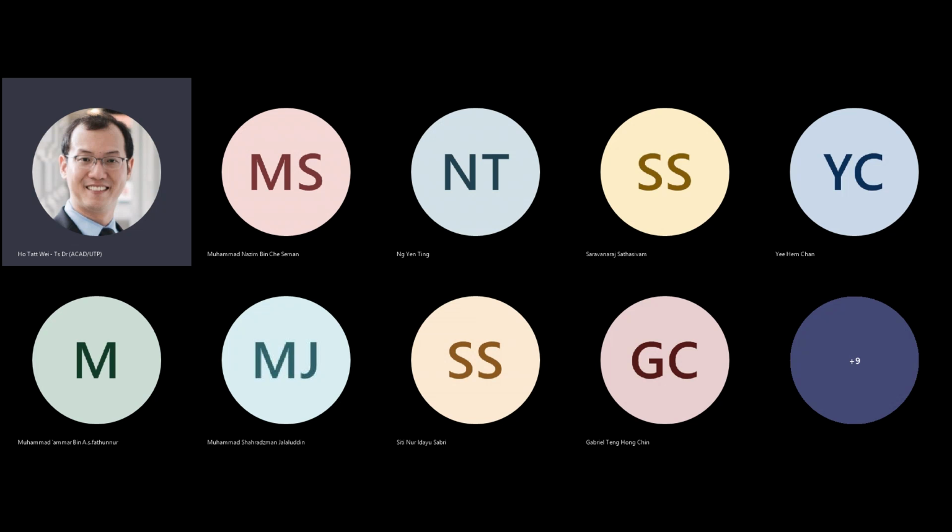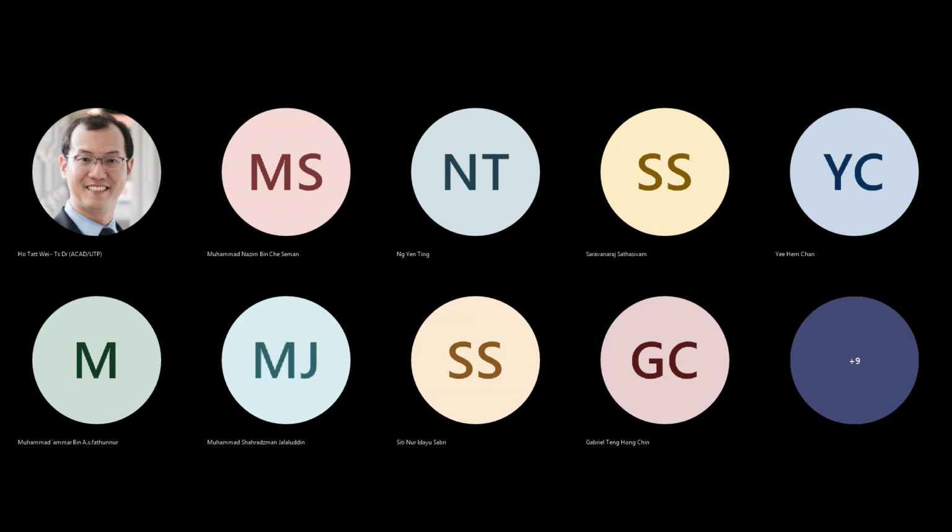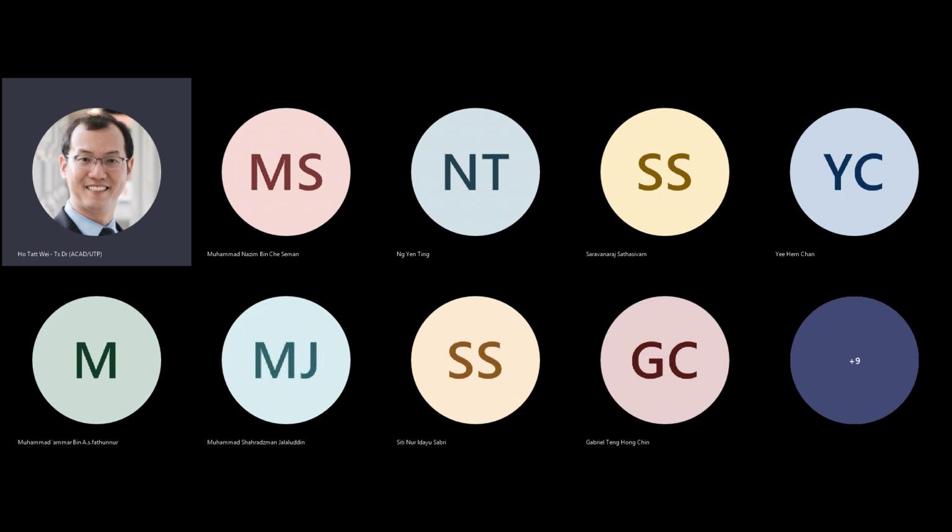That's not strictly true in today's nanometer size gates, because the transistors now don't actually have a flat channel. The channel goes something like this, and then this is your doping, and these are known as FinFETs, or sometimes 3D MOSFETs.